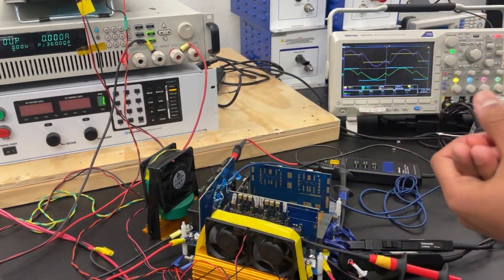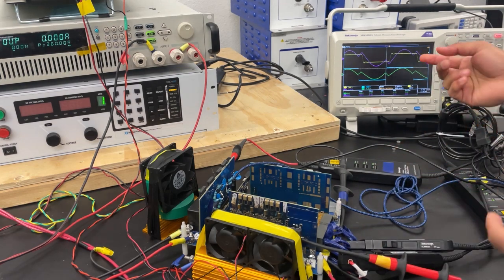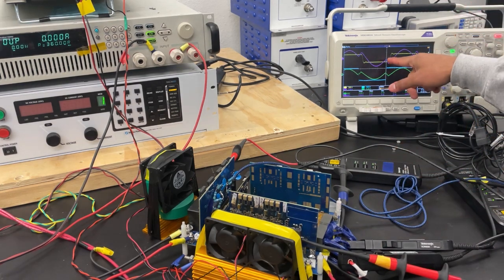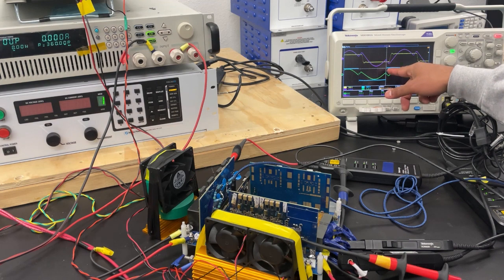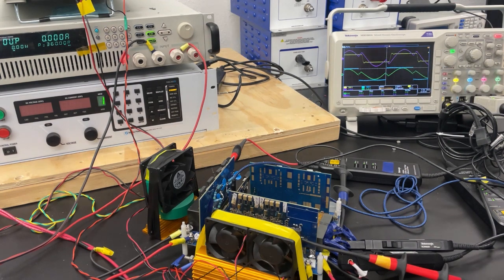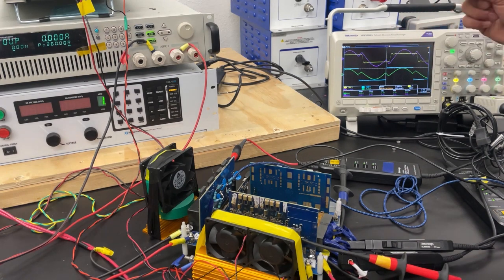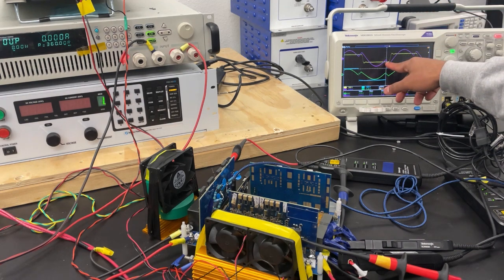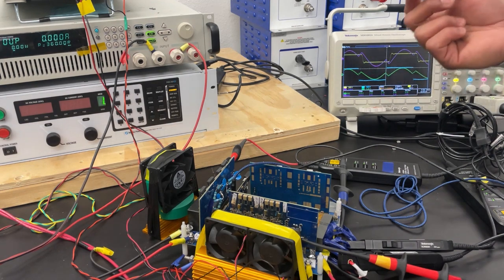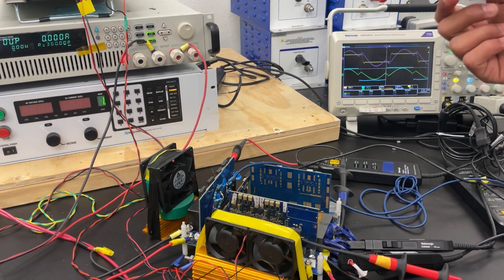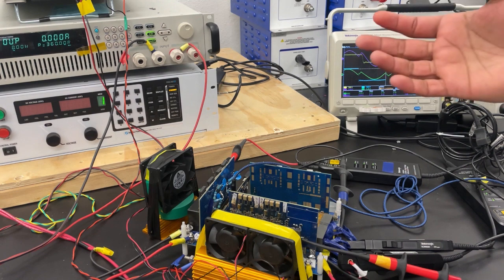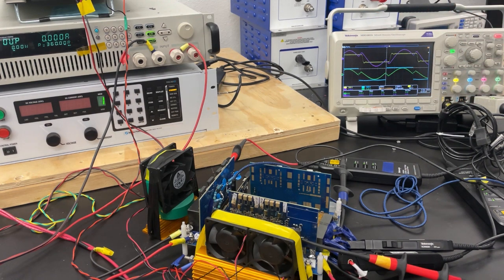It is important to understand the orientation of the currents if you want to analyze this waveform. Yellow is VP, blue is VS, pink is IP, and green is IS. When the transition happens from minus Vin to plus Vin on VP, we know that switches S1 and S4 are turned on. At that time, we can see that during the transition the current is negative. That negative current ensures that the output capacitance of devices S1 and S4 is discharged, and that ensures a ZVS turn on.